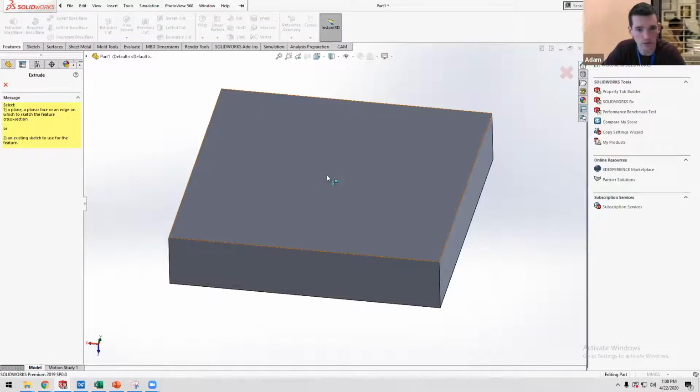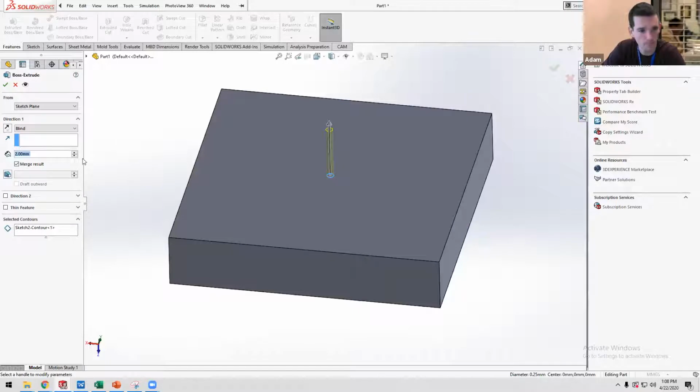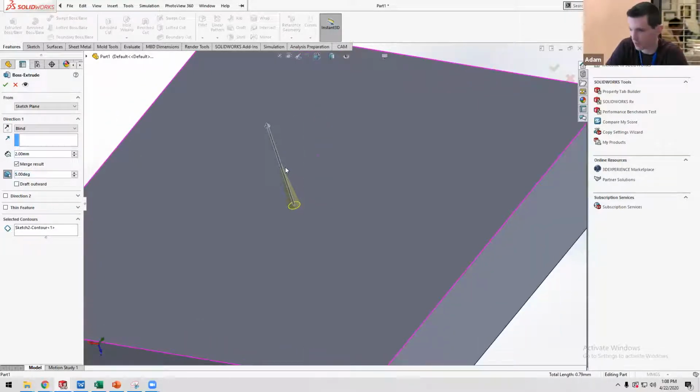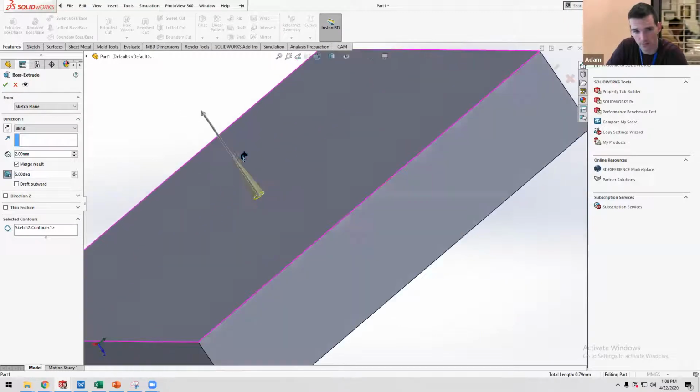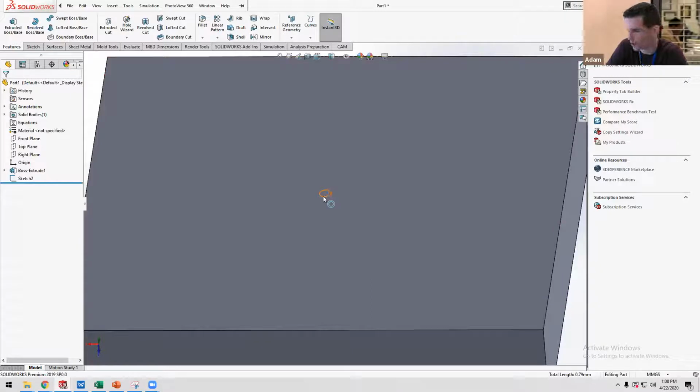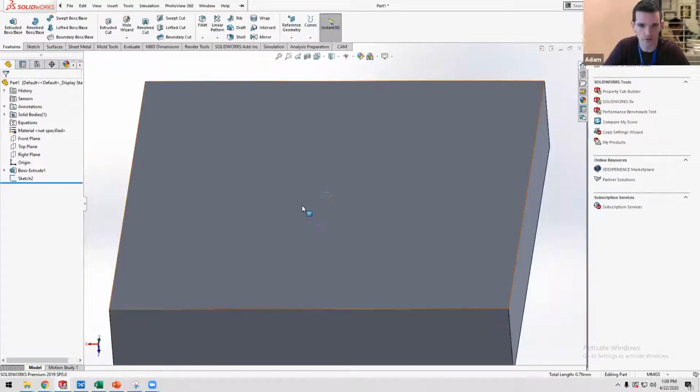If I was going to extrude this little cylinder, I can't really make it a cone unless I'm adding a draft angle like this, right? And then it depends how many degrees I put as to how high it is, the height of it. And I don't want to mess around with that. So instead of that, I'm going to do a loft, which essentially means I take two sketches and I connect them by their exteriors. I take two profiles, I draw lines between them. And so I will show you that.